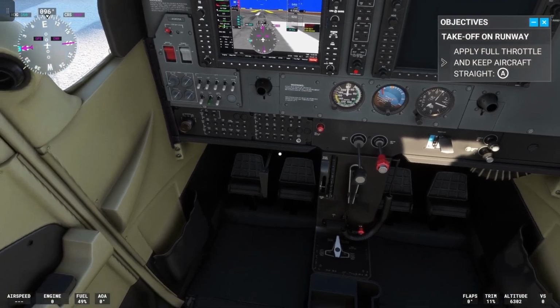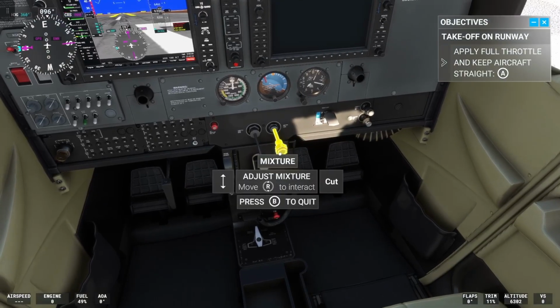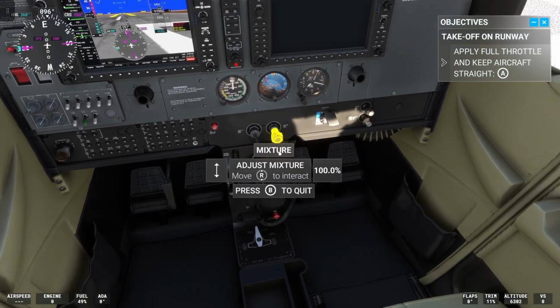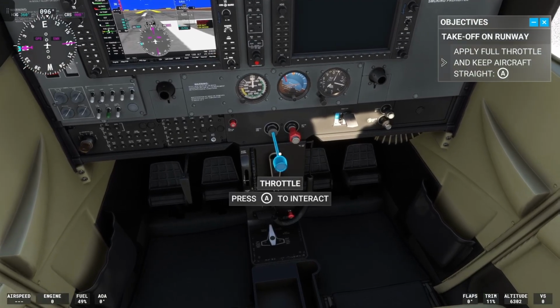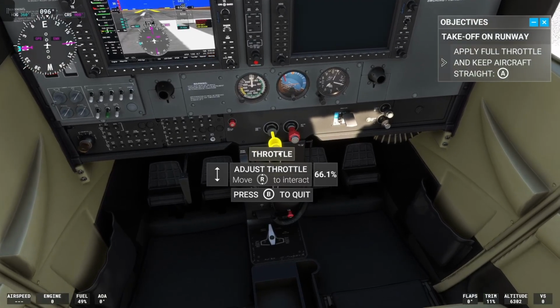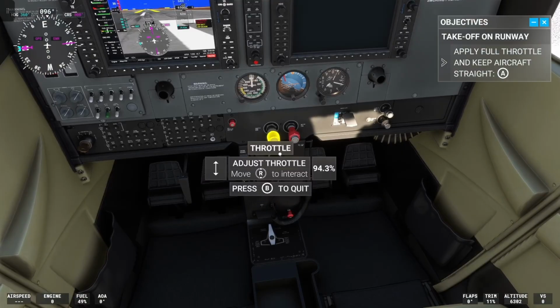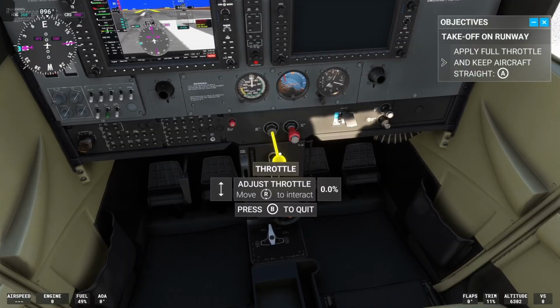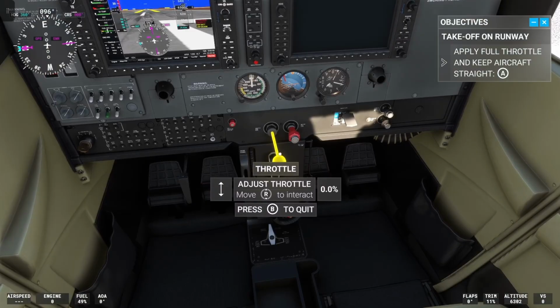Brakes are set. That's what it will look like. They are set. Brakes are set. That is a check. Now we go on to the starting engine phase. So mixture, the red knob here. Mixture is rich. Rich is 100%. That is a check. Now we want to prime the gasoline right next to it. That's the throttle. 100, that is 1 prime. 2 primes, we want 3. And 3. Now we leave it open at 1/4.